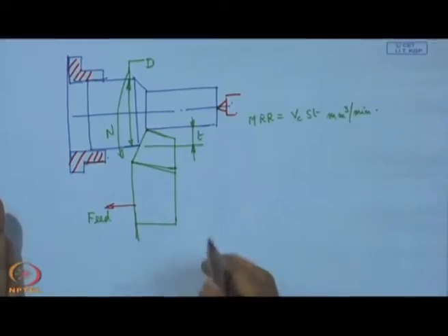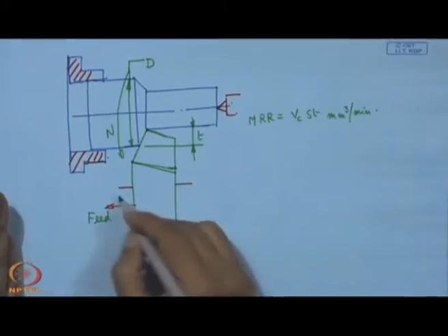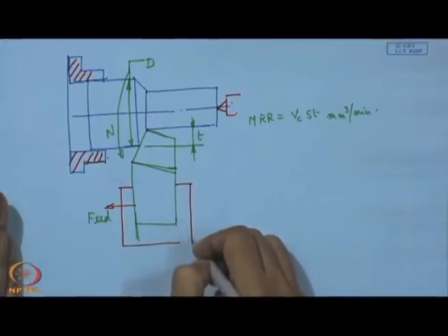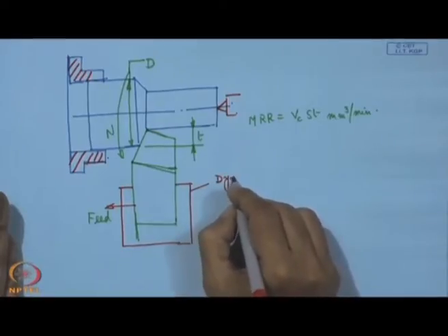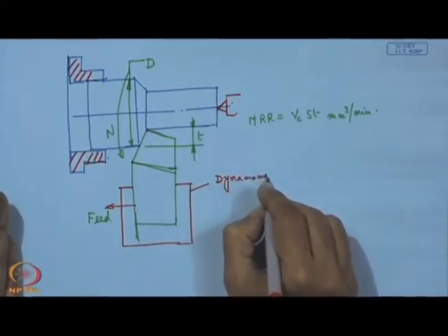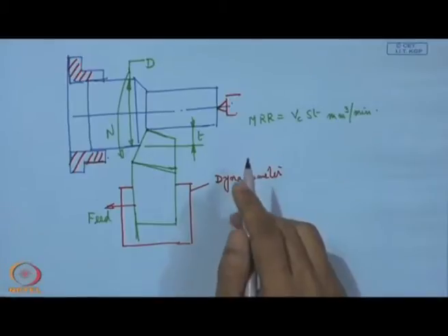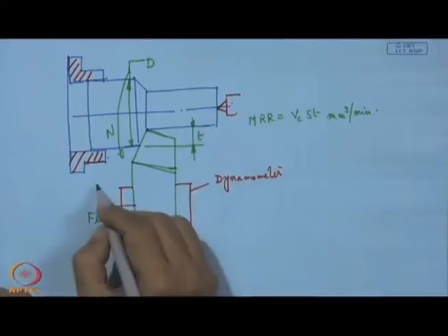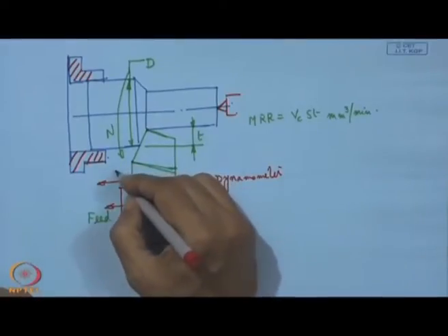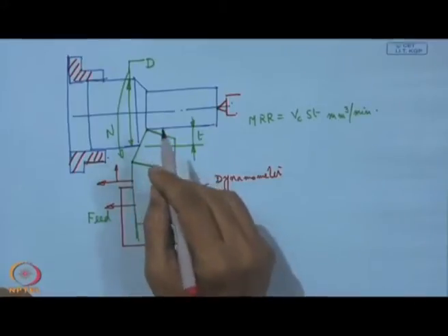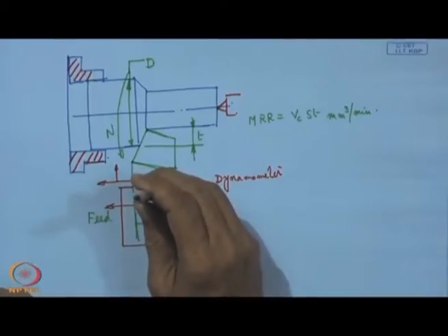carriage on the tool post, but over that there should be a dynamometer. So, this is going to be the place where we put a dynamometer. This is actually a turning dynamometer, which can record the force in 3 orthogonal directions. That means in this direction, that is the longitudinal direction, in the transverse direction, that means the radial direction, and in the direction perpendicular to this paper.